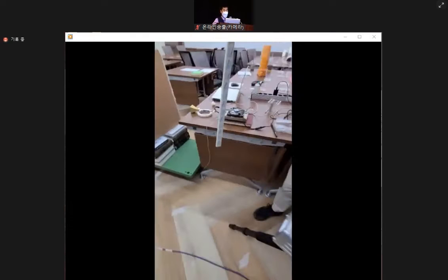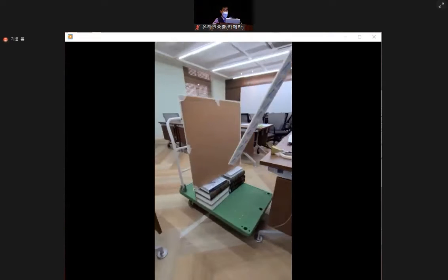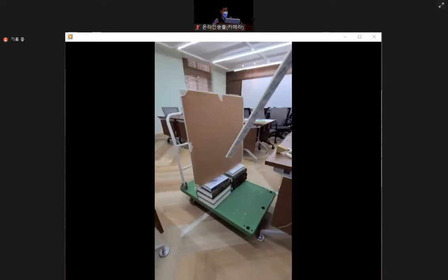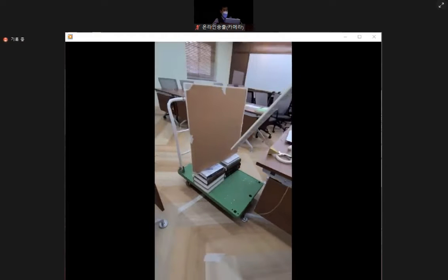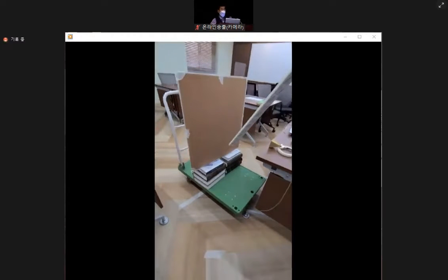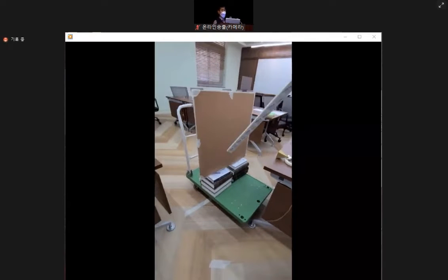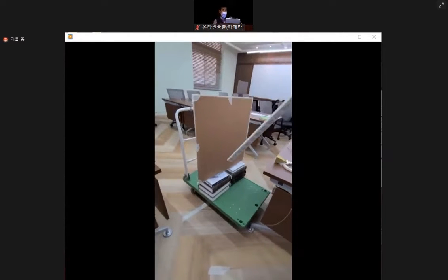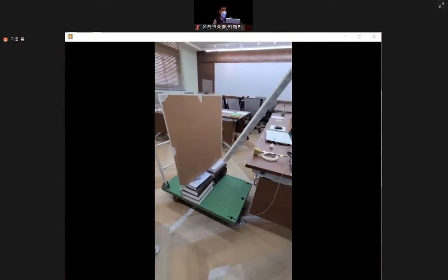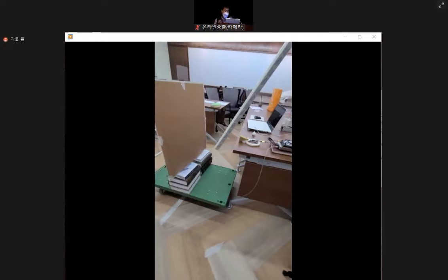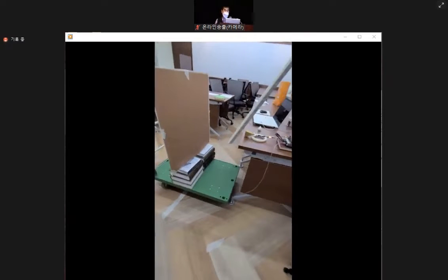Remember, in the previous test, at a little bit lower angle from the 41 degrees, such as 20 degrees, the signal strength was not ignorable. Why? I told you the near zone area is polluted with a lot of noise. We changed the angle of observation from 45 degrees to 20 degrees, and we expect a decrease of the signal strength of the received power.